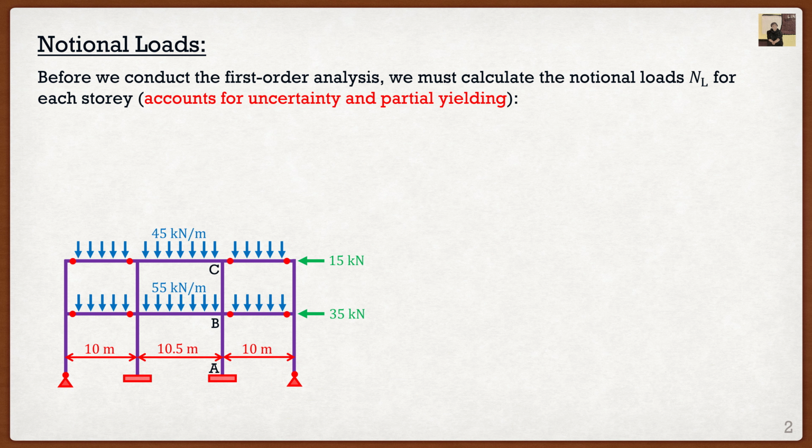The first thing we are going to talk about is notional loads, and these are going to be very important because whether you're doing the simplified method in CSA where we do a first order analysis or you're doing a second order analysis, these notional loads need to be calculated no matter what happens.